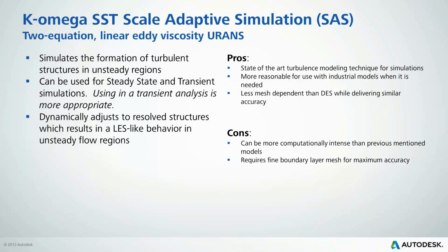In terms of cons, it's still computationally intensive, similar to the LES, and still requires a lot of refinement along the wall, but the sensitivity of the mesh growth from the wall into the flow domain isn't as sensitive. And this is really the state of the art. It's only a few years old, and for some of our models that we've done, it's shown to be very, very powerful.